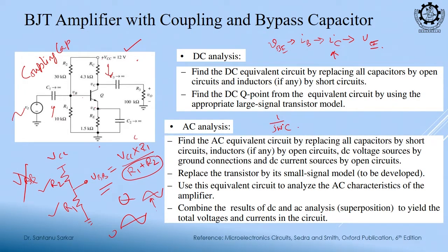Right. So, if your omega is high, what will happen? This impedance will go down, right. So, if omega is very large, this will go close to 0, and 0 means it will behave like a short circuit. So, where should it behave like a 0? At the frequency of interest. This signal should have a frequency, no?